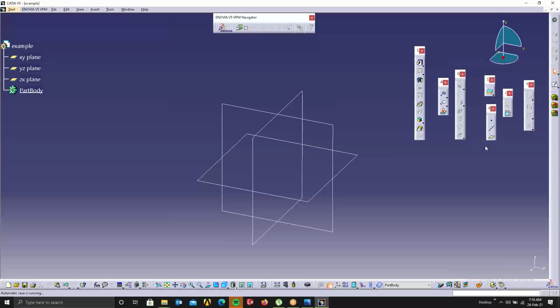After creating the step file, if you create it in Catia, then in SolidWorks you have to use recognize. There's one option, recognize. Using that, it'll recreate it, meaning it'll try to understand the design and create a model out of it. That model you can edit, directly from Catia to SolidWorks.